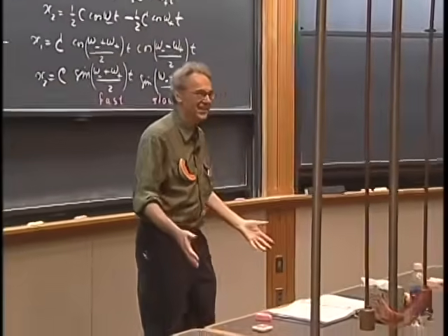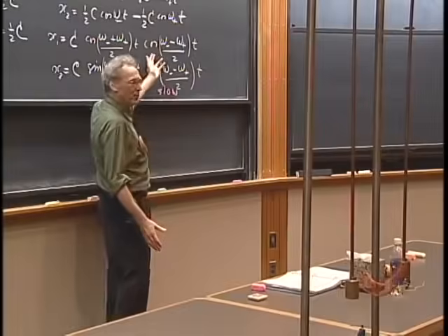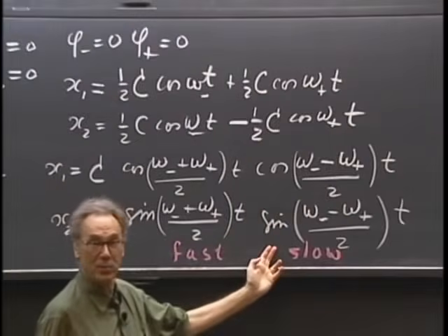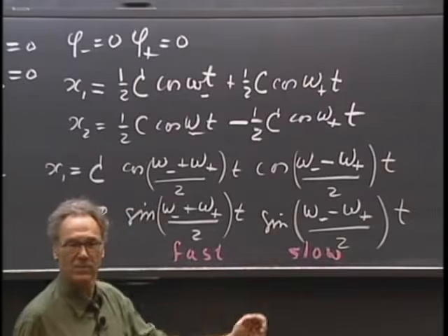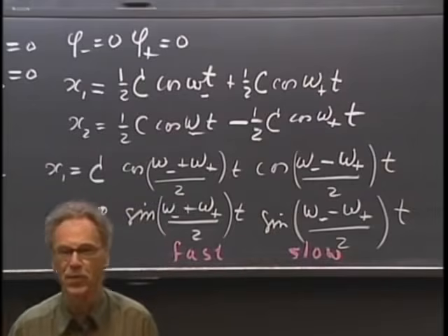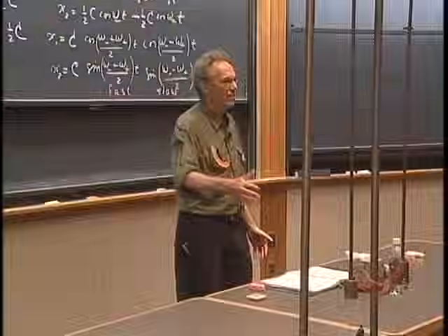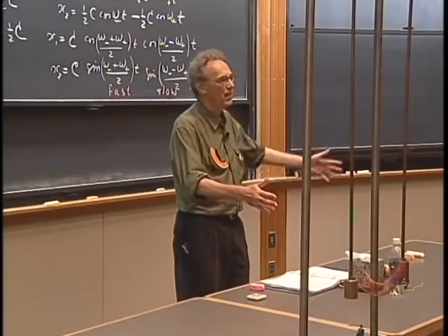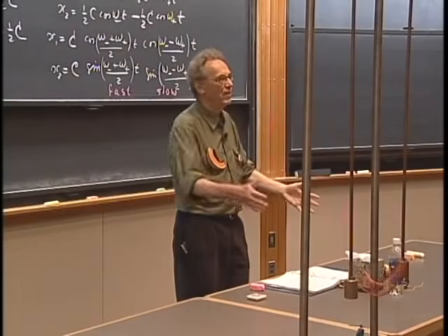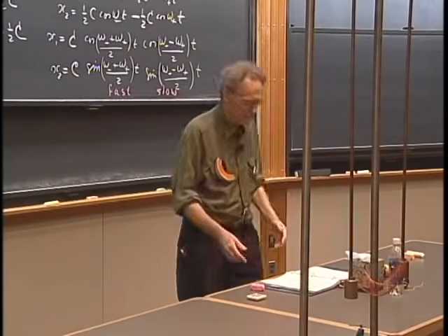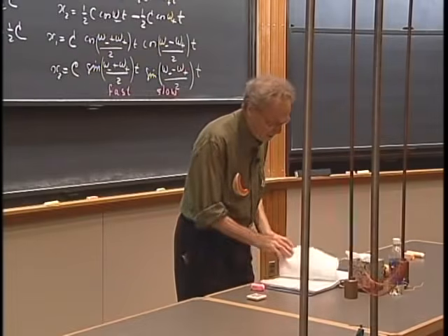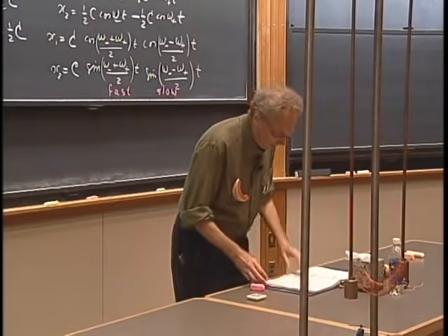And then a little later in time, the cosine term will become -1, so it starts to oscillate. But when that happens, the sine term is 0 again, so it stops. So you see a beautiful beat phenomenon. The first one will gradually come to a halt, and the other one will pick up, and then the other one will come to a halt, and then it transfers, in a way, energy. It is, of course, consistent with the conservation of mechanical energy.